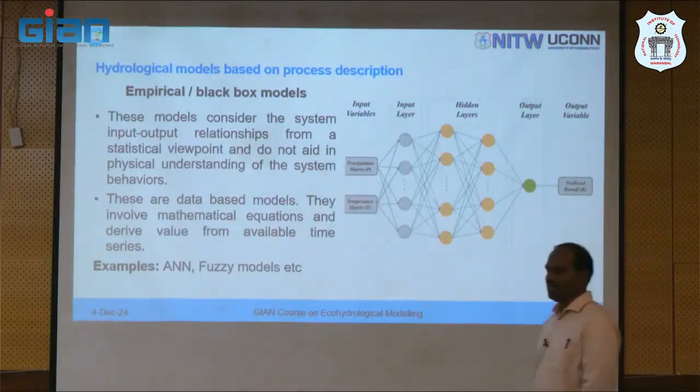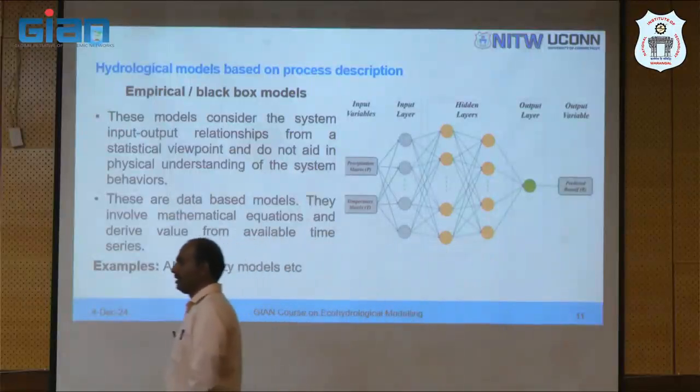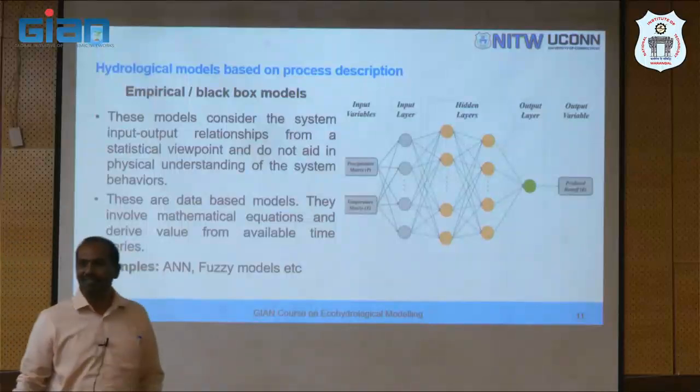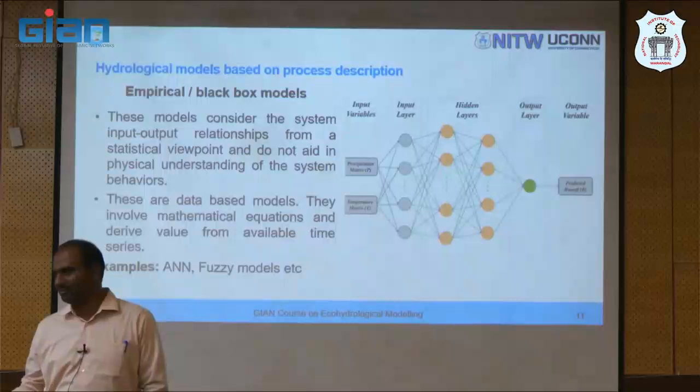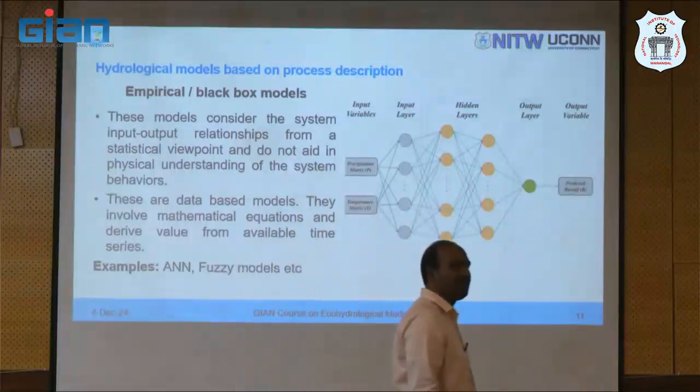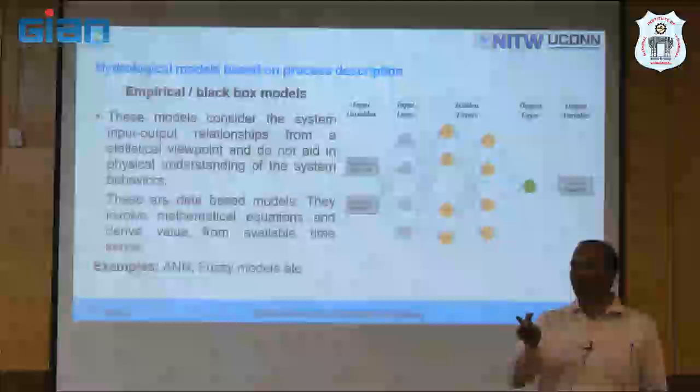What about the rational method, rational formula? Is the rational formula empirical? I would say it is derived. It's a simple model, but it's derived, right? It equates input to output. At the time of concentration, the input to your watershed is rainfall intensity. What is this rainfall that is coming? Some millimeters per second or centimeters per hour. That multiplied by the watershed area gives you the volume flow rate that is coming in.